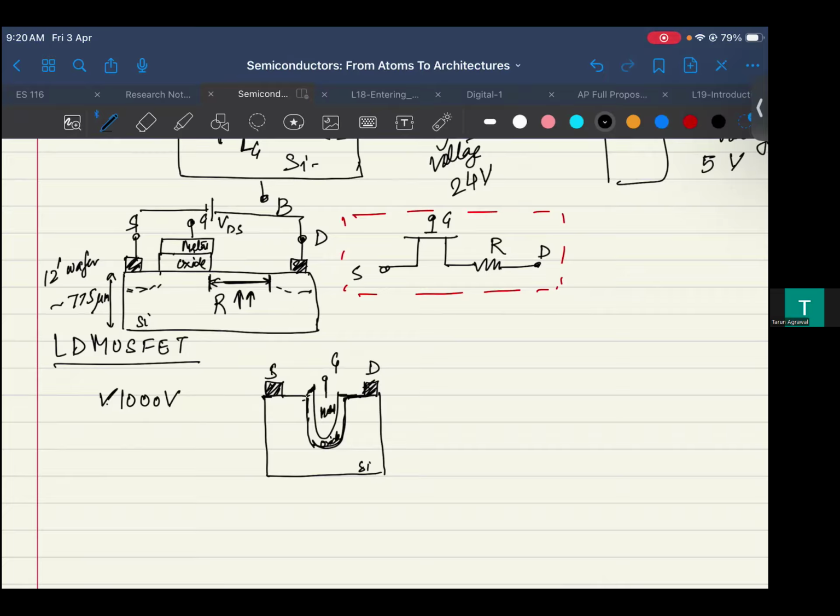And then what would happen when you are applying a very large voltage? You see this is going to drop across the trench, or the vertical direction of the MOSFET, and there is a large region there. So you are not limited by the dimension, let's say how much transistor footprint you can increase, right? So this could be something which is considered for very high voltages, which we know as the vertical or trench FET, right? So that is another avatar you can see, because you want to handle very high voltages, let's say around 500 to 1,000 volt.